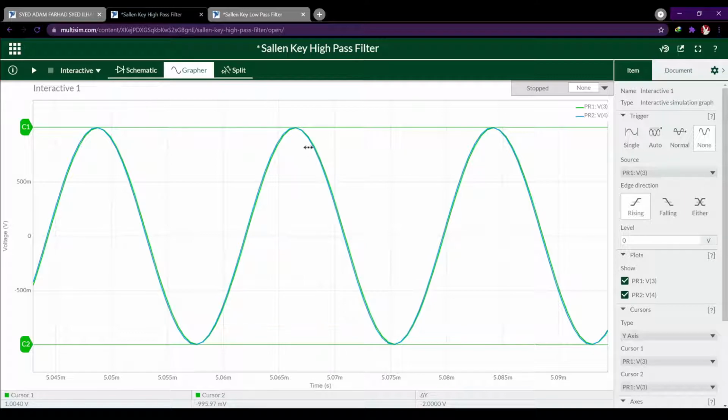It is like joined together with the voltage input because the value is very close. That's why you can still see green here. It means there's still a voltage output which is very similar to the voltage in. So we get a 2 volt voltage out, which means we have a gain of 1, since voltage out over voltage in is equal to the gain.